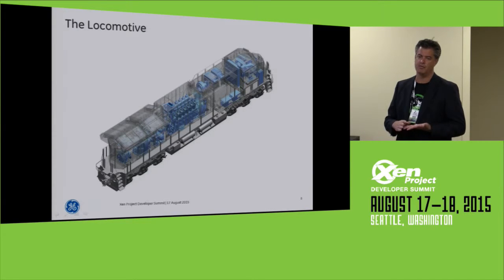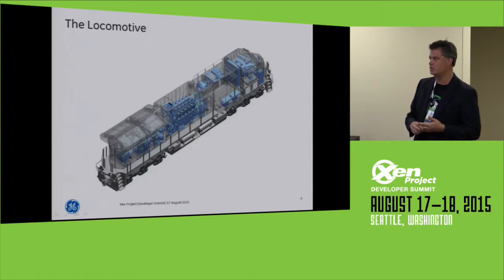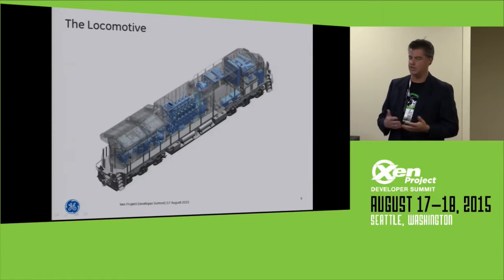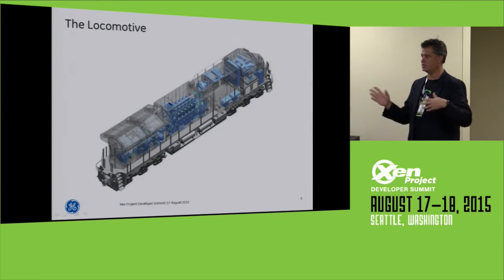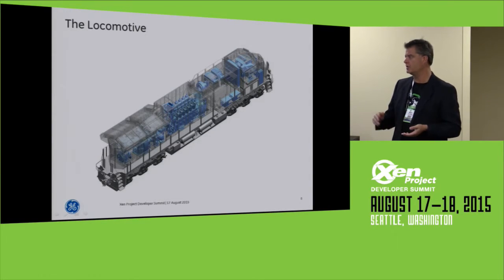I don't know if you've ever seen that before. GE, that's part of one of the things that we do in our group in Melbourne, Florida. It's called distributed power. So there is nobody on board that locomotive there in the back. It's not wired, because you can't run a wire that long and it'd be difficult to maintain. That's all wireless control. So it helps because now you've got locomotives pushing at the same time you have locomotives at the front pulling. So instead of having a huge amount of drawbar force between the last locomotive and your cars, you can basically distribute it, saves fuel, saves wear and tear, et cetera. So that is one of the products. That is what's considered a cab electronics product.